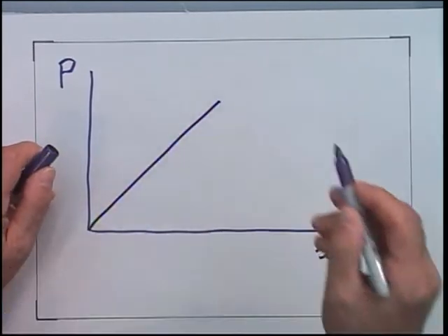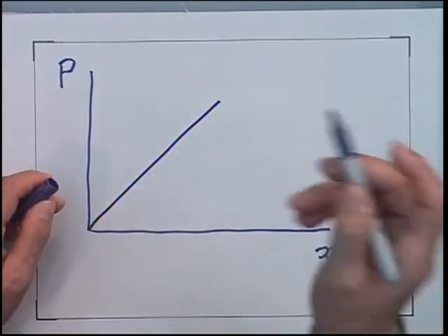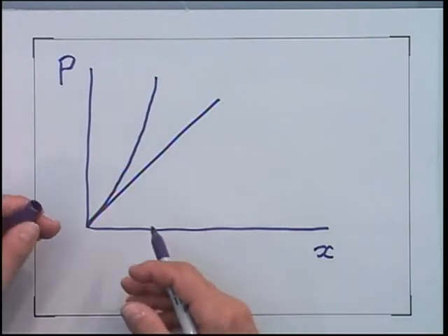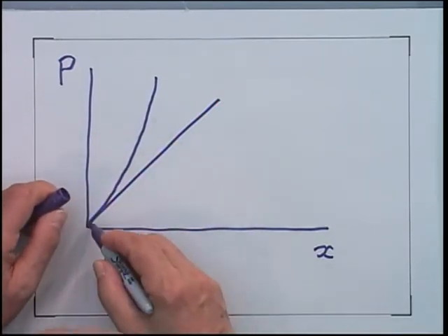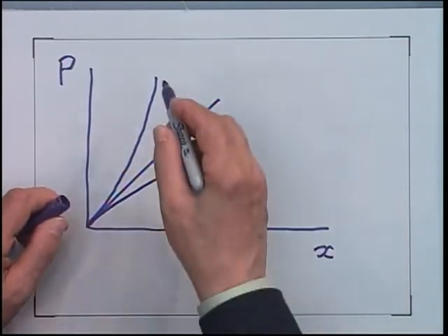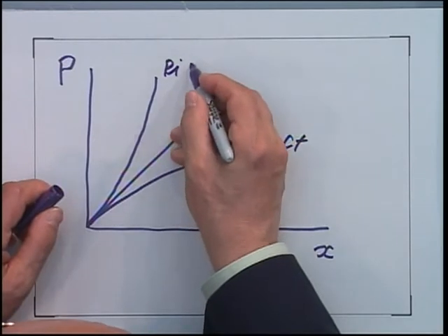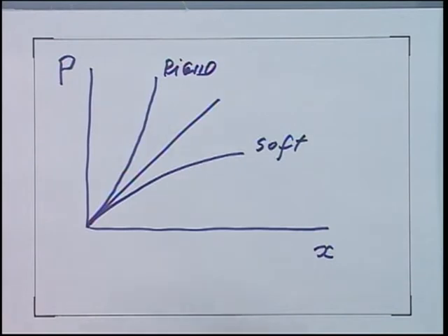In a linear system, certainly we have something like that. In a nonlinear system, the system that we were examining for several hours, it looks like this. So the system becomes stiffer and stiffer when the displacement increases. But there are also systems with a soft characteristic of the restoring force. A typical soft characteristic of the restoring force is, for instance, for a ship in her roll. At certain significant angles of the heel, the restoring forces go down. So that's a nonlinear characteristic of this type.